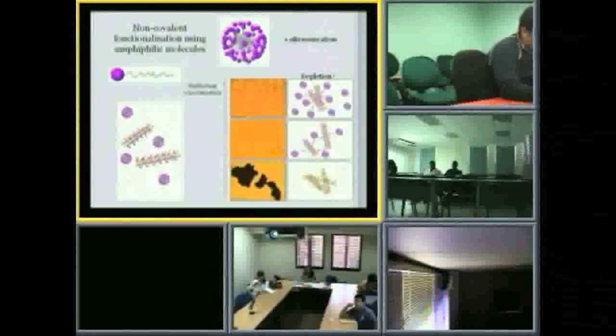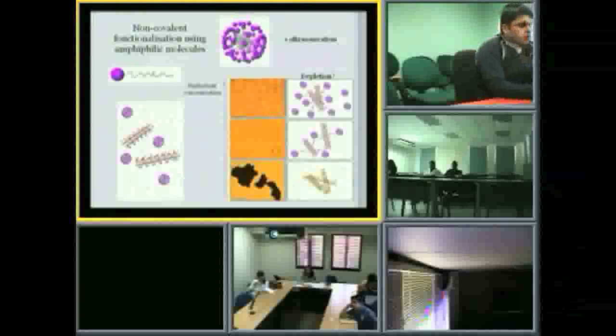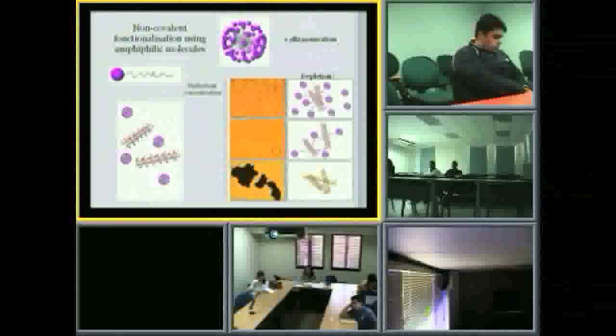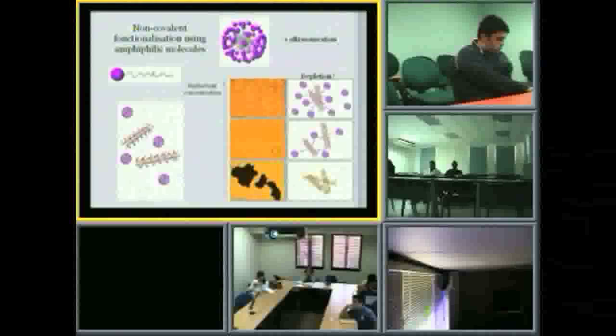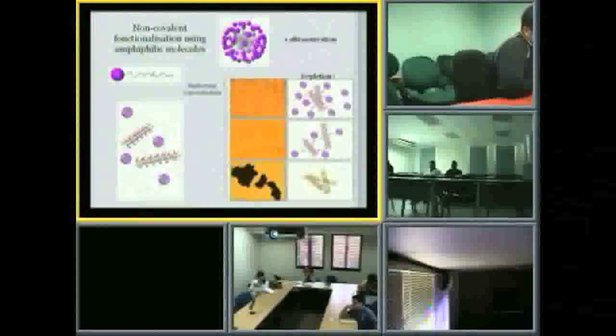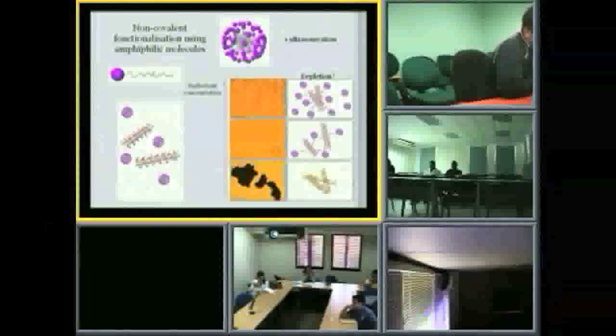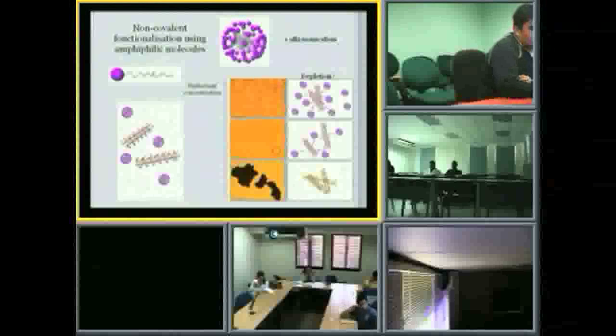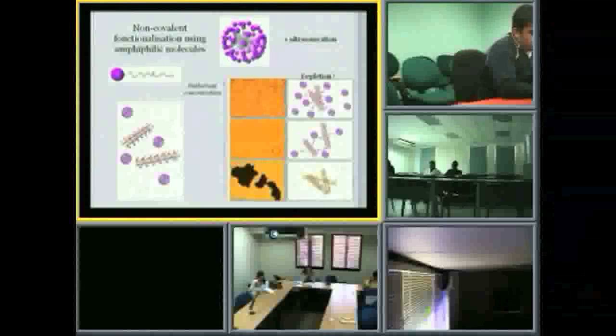You have to remove this surfactant after you disperse the nanotubes. What method do you use? It depends on what you want to do after that. In our case, we take these dispersions and then we make fibers of carbon nanotubes with them. We can discuss details after if you want, but in this case, we replace the surfactant by another polymer at the surface of the nanotube, which plays the role of a glue between the nanotubes. But it depends on what you want to do.